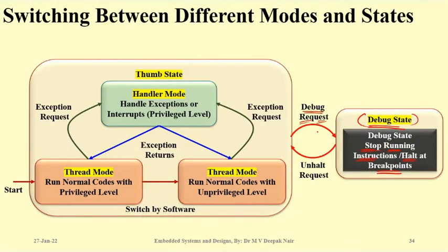This is all the journey of your microcontroller's program. It starts in a normal way, goes to handle the interrupts, may return to the normal mode, or may return to the normal mode with unprivileged levels. Or in between that, if you want to stop the normal running of the program, you can enter into the debug mode and you can stop the normal running of the instructions. You can call it breakpoints. I hope most of you might have used breakpoints in C programming.